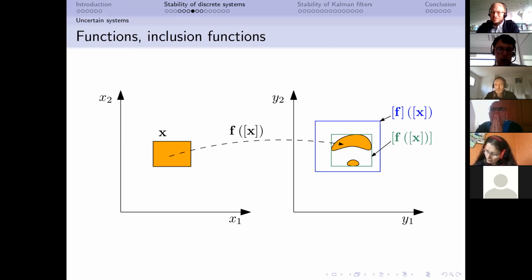But what you will quickly notice is that for most complex systems, such as robots, that have a state vector larger than 3 variables with quite a lot of nonlinear functions, after, say, 5 iterations, the box is already minus infinity plus infinity. So you can stop as soon as it reaches values that are not meaningful anymore.